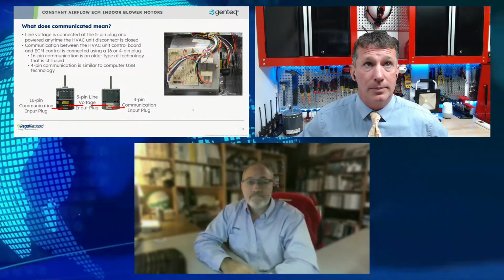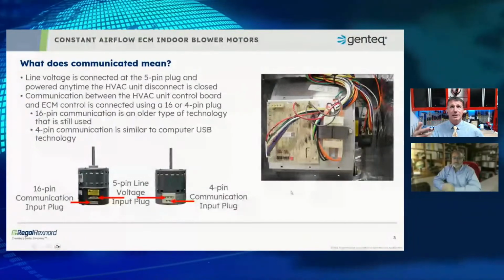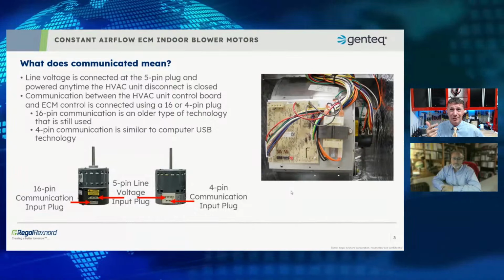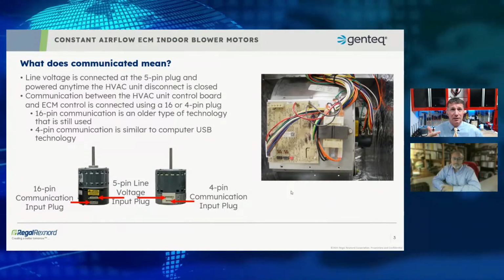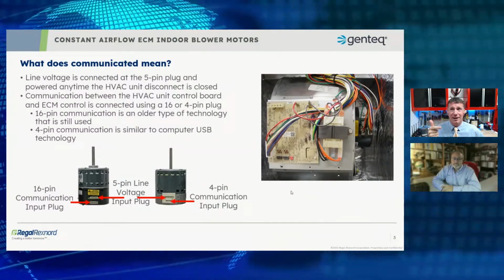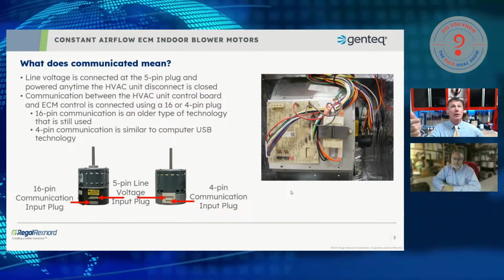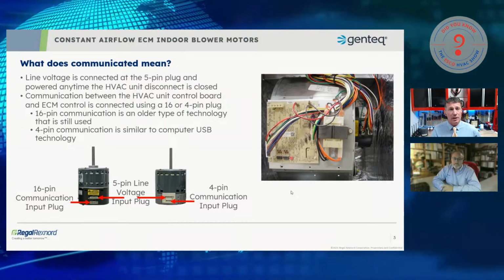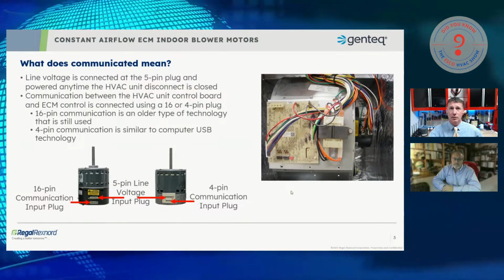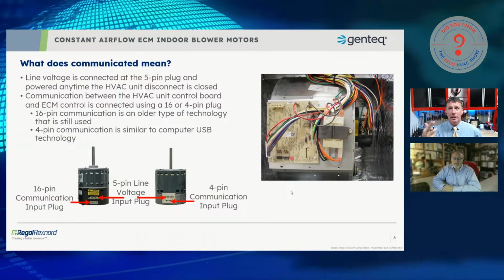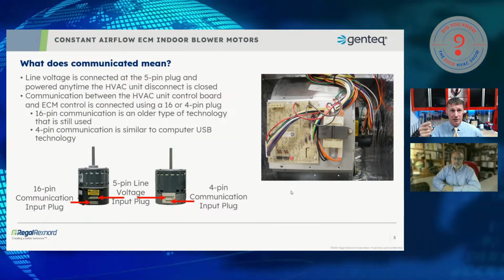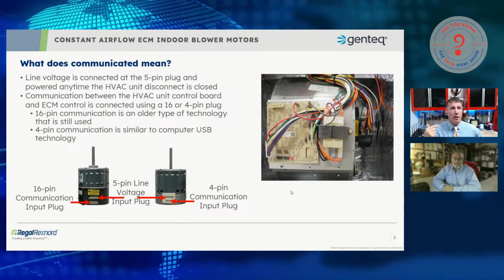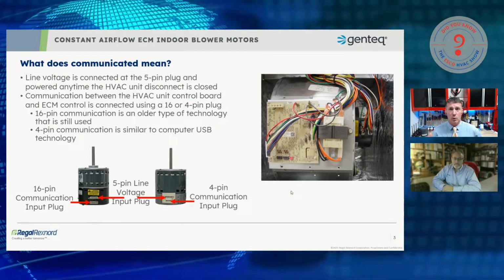Absolutely. Well, and like when we talk about things like pressure transducers on an inverter system, or even your pressure transducer that is on your digital manifold gauges, we've got a hot, we've got a common, and then we have a variable coming back. So when we start getting into serial communications, that's typically what we're talking about. We're talking about supplying a constant and returning some kind of a variable so that we can talk both ways. Sometimes we have the extra where we can variable forward and variable backward. We're just talking back and forth on a simple wired connection.